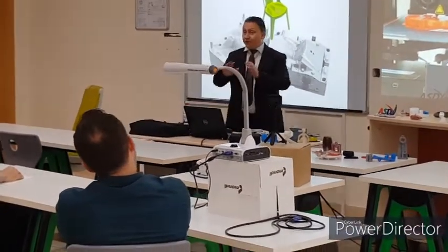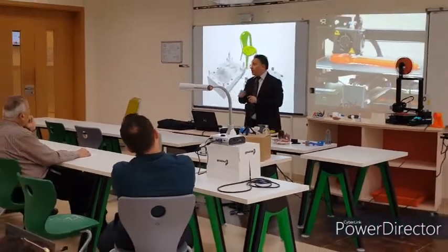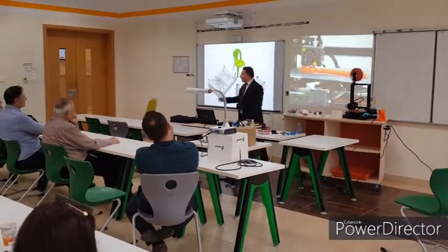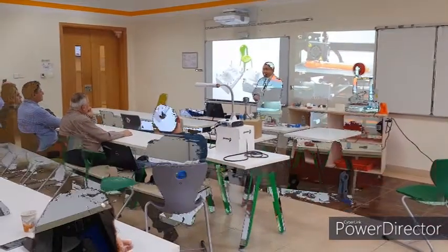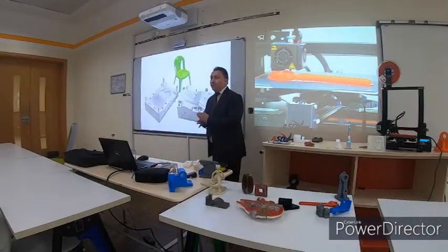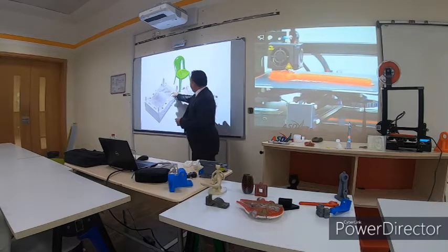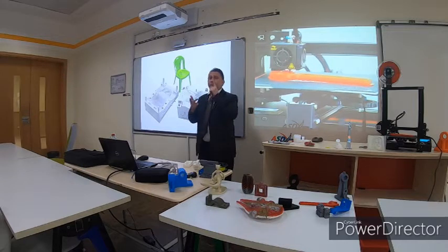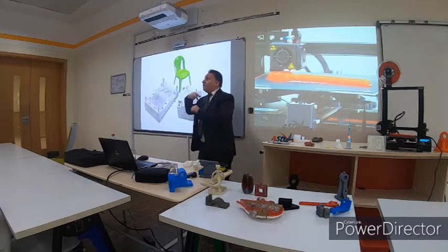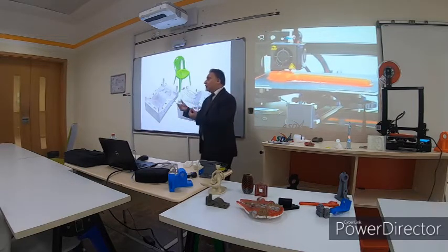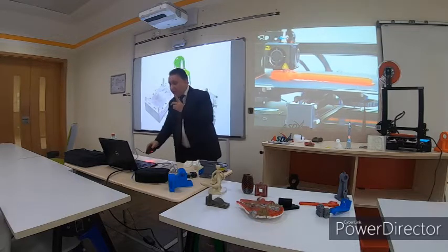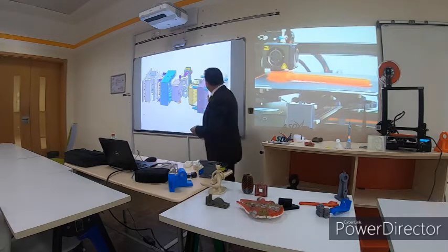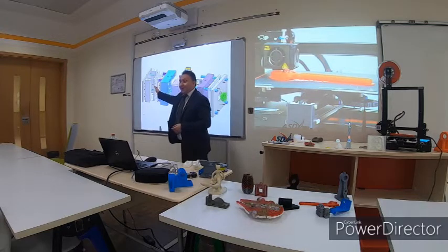Before my first job in 2011, I worked as a mold designer. So this is my area, injection mold design. It is a very difficult technique, because you need to care about the quality, where to put the metal, where to put the plastic, how to eject the plastic after you mold it, and how to make the cooling for the product.